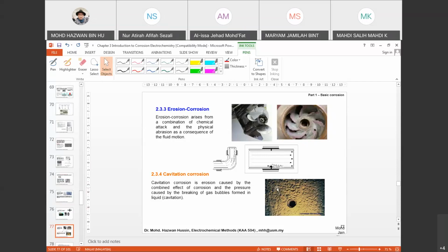So if you put a high velocity of liquid, and then it goes to another big container, it can easily form bubbles. Bubbles will be attached on the walls of the container, and this actually can trigger corrosion because inside the bubble you have gas. So all this can be seen here. It forms a very rough surface, meaning that this was previously attached by bubbles.